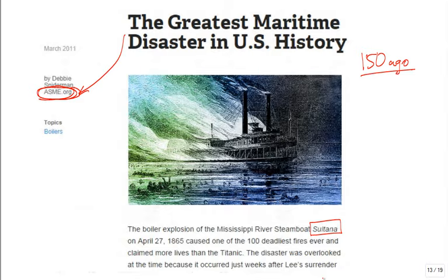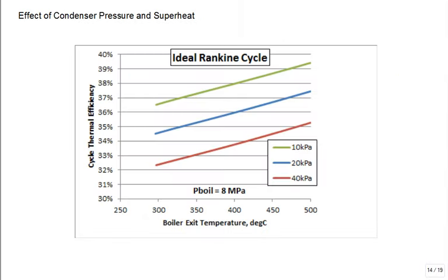So, all right, here's looking at condenser pressure. The challenge with condenser pressure is finding how you reject the heat. We reject heat to lake water often, or river water, not so much in Texas, or ocean water, not so much in Texas, or actually to the air by evaporative cooling or something else. But often in Texas, our big power plants build a lake for it, and they reject the heat to a lake. And that lake temperature is low, but you can't make it any lower.